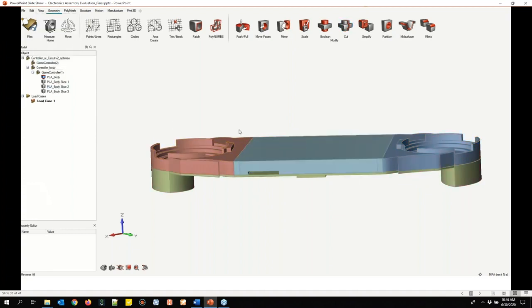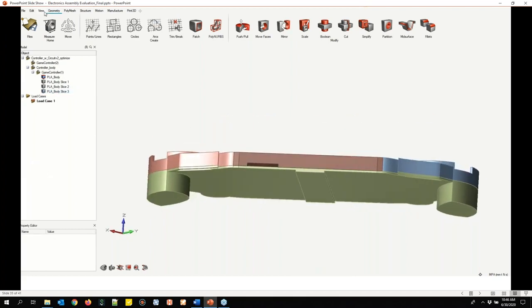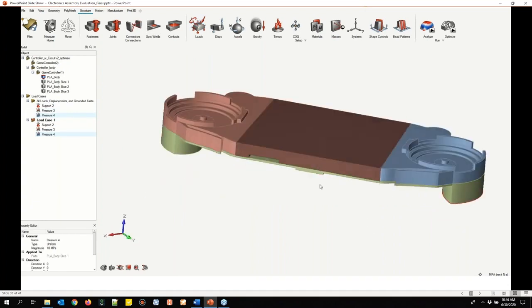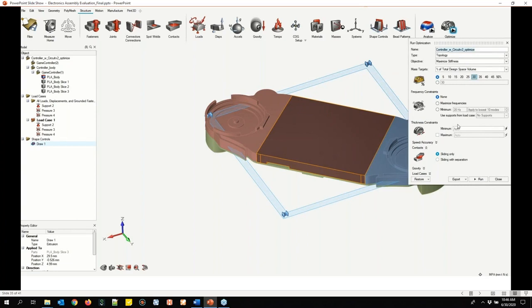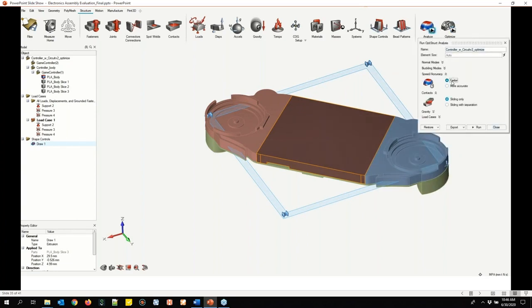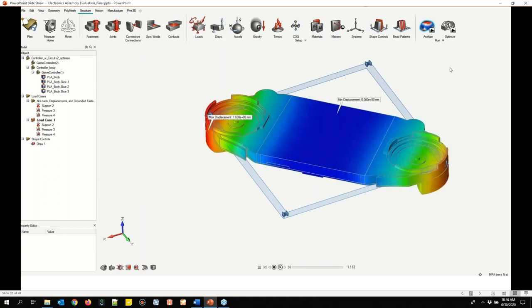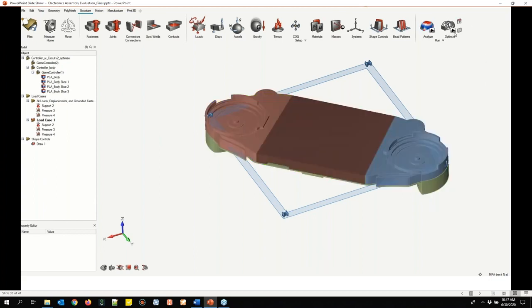So finally, now that we've had our models set up for this design space, I now want to select that middle part that I just extruded and make that my design space. In essence, we're going to run a baseline analysis, just to see what the baseline benchmark is. And this is an overly stiff design because we've filled up our entire back space area to have a thickness to the height of the controller. So we're going to set up an optimization later, but we're going to first run this baseline design to see what our results are. And this is going to be an overly conservative design. And again, the objective of what we're trying to do here is to achieve some sort of stiffener pattern, what makes sense as a stiffener concept, and have the tool inform us of where to place stiffeners. So here are the results for our baseline analysis. And again, this is the overly conservative design, so we can see our different stress and deformation here.